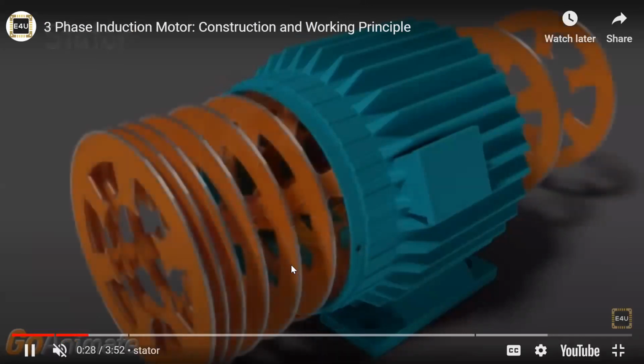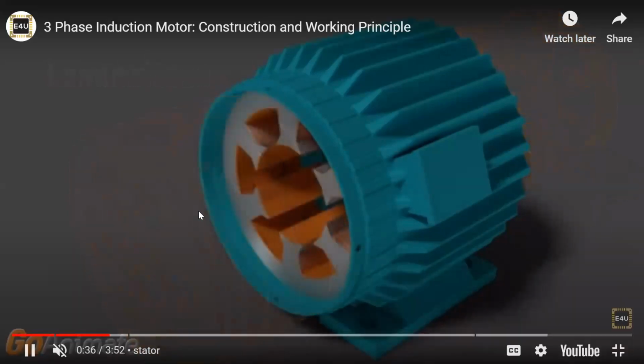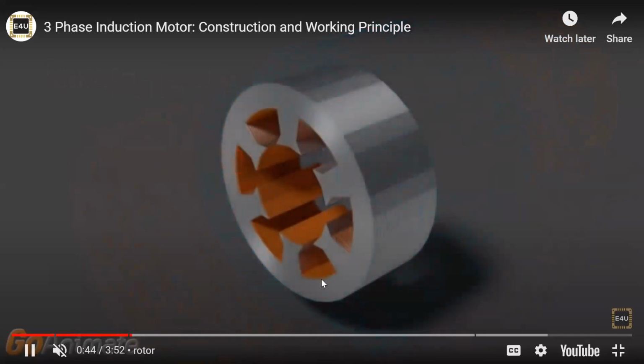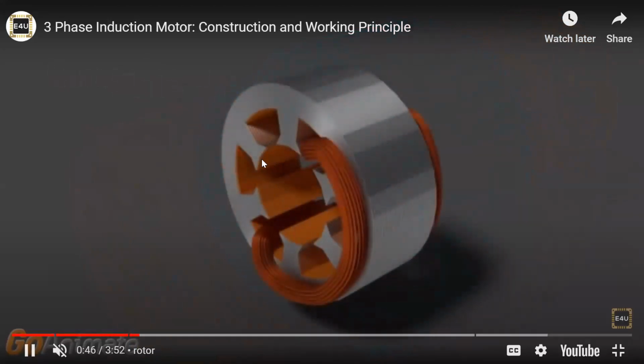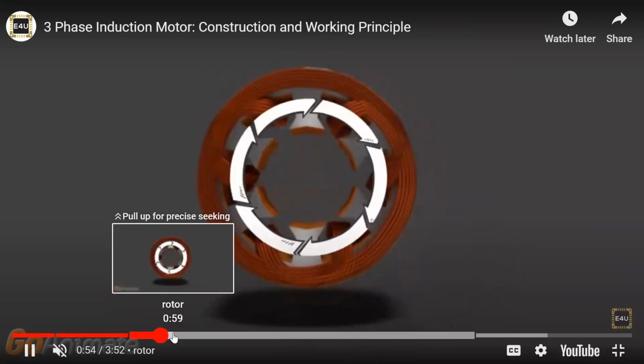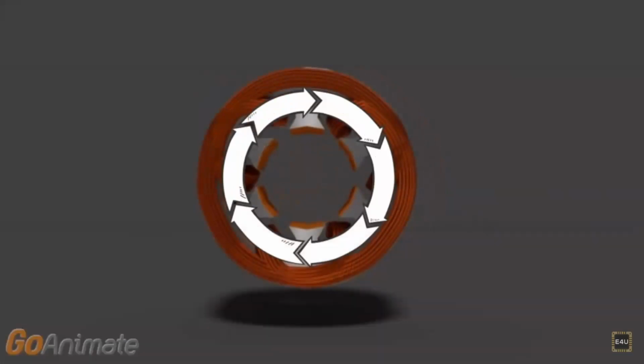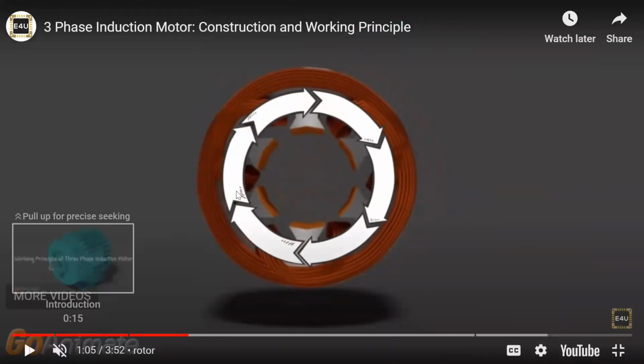And inside we have the silicon steel stampings, laminated. A group of stampings are taken and slots are formed. In these slots, they wind the wires, in an RYB star connected network or an RYB delta connected network. This is how they are winding in the stator. So these are the construction details. We'll pause here and get back to the slide.